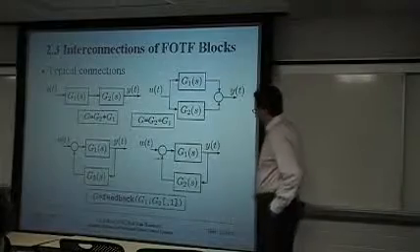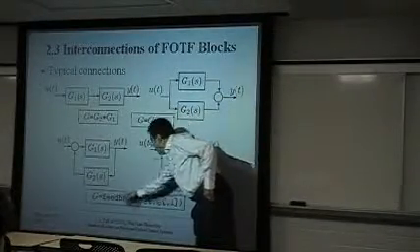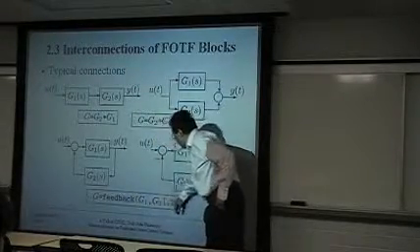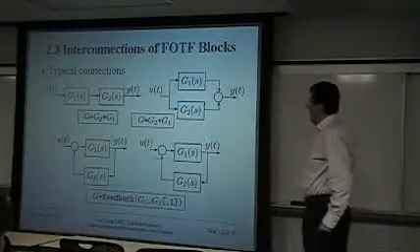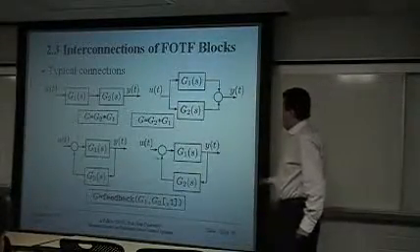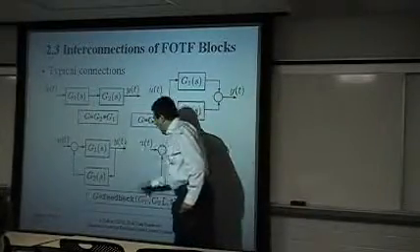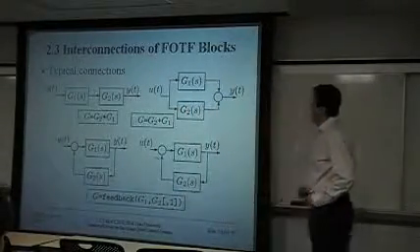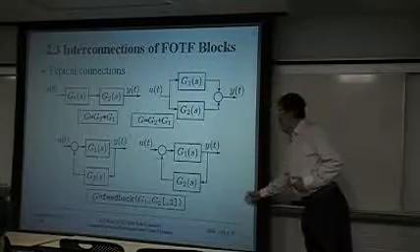If you are using a negative feedback, what you need to do is to call the function feedback, which allows you to give G1 and G2 and leave the rest of it. Then you can get the overall system from U to Y. If you are using a positive feedback, you must have a 1 here as a third argument. So this is the definition used in the control systems toolbox.